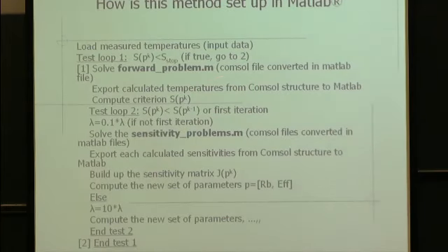So quickly, this is how I implement this procedure in MATLAB by using COMSOL. Here, this COMSOL problem, you can save it in MATLAB form. Afterwards you can use it in MATLAB to export data, set the parameter you want to estimate, and make a computation all the time. It resembles the loop I showed before.